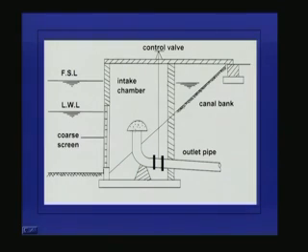Now, the total height of the depth of this entry is kept such that the top of this entry point is above the low water level, so that water can flow into this even when we have a minimum amount of water in the canal. So, this is what we call a canal intake structure.